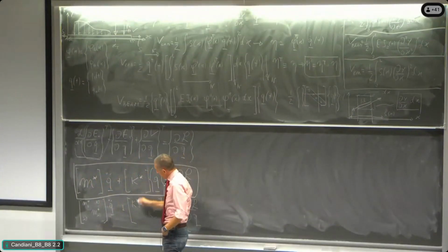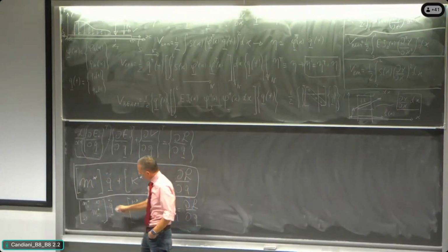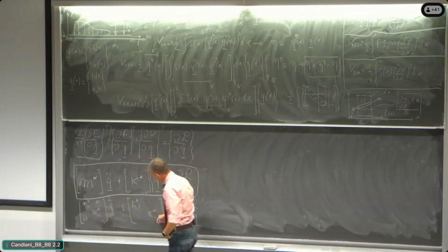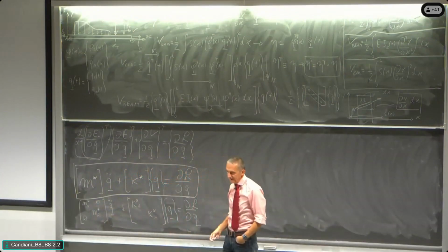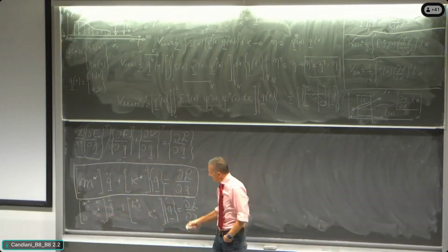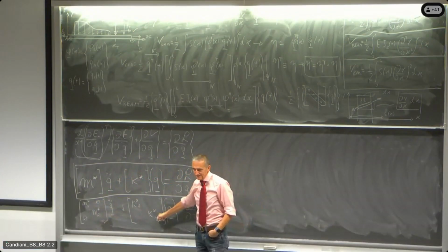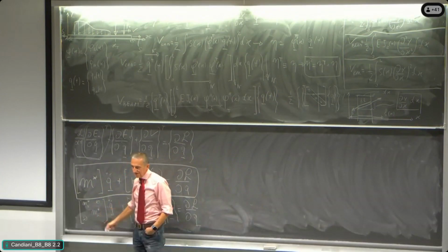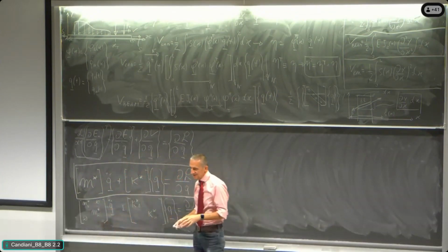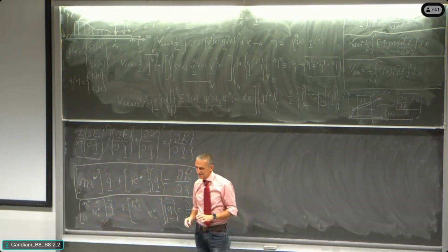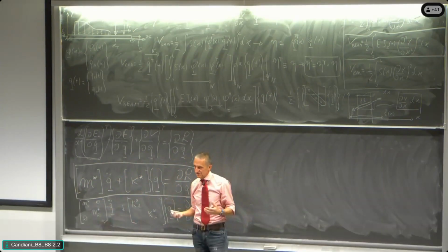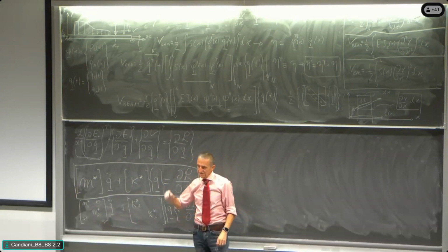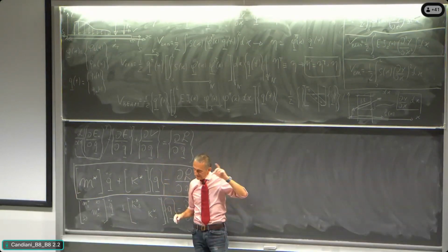Those quantities called K star 1, M star 1, K star i, M star i are actually the modal stiffness of the i-th mode and the modal mass of the i-th mode, and so we have in our hands the numbers that are representative of the concept of modal stiffness of the mode and modal mass of the mode.